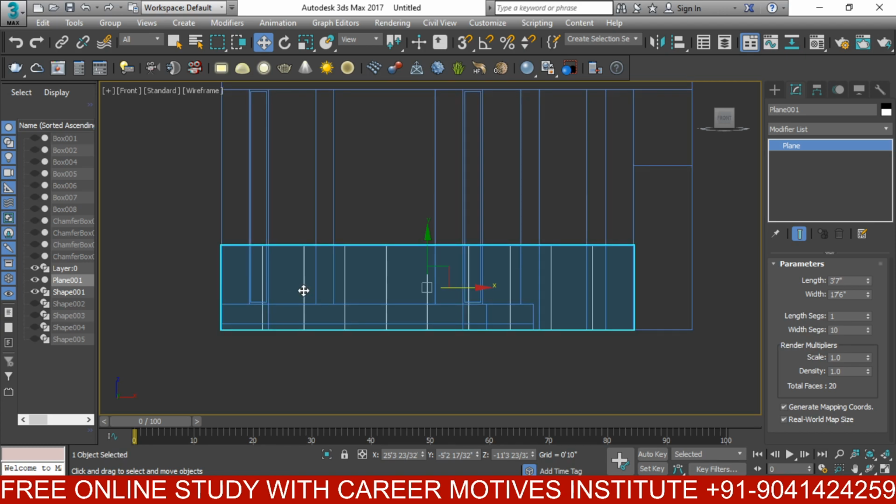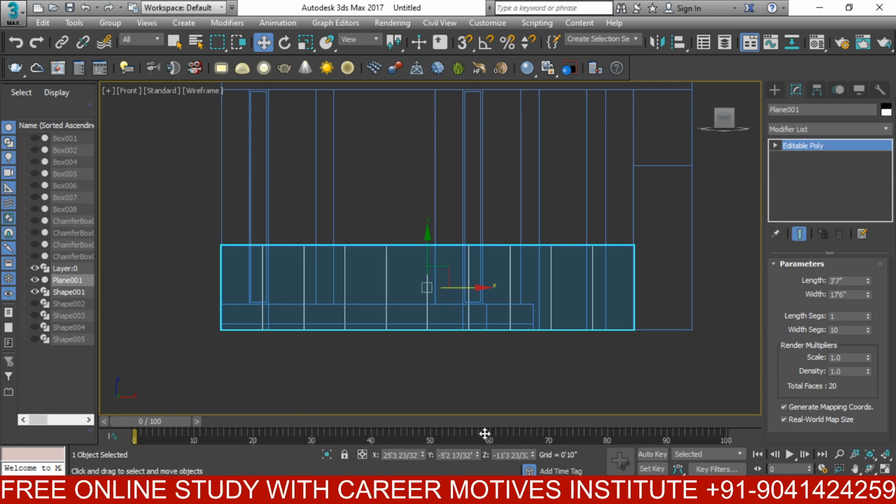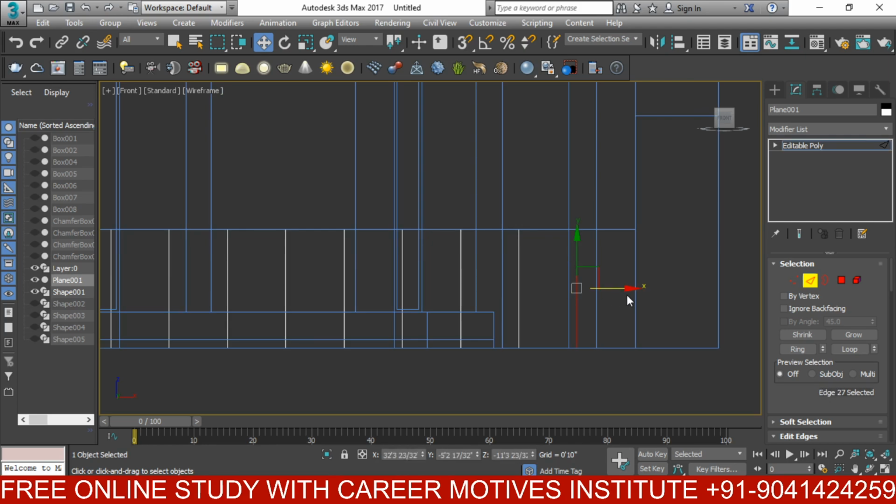So what I have to do is right click, convert to editable poly. I'm going to select edge. I'm selecting one line and move. I'm selecting the next one and move, like this. It's very easy and very smooth and not that time consuming.